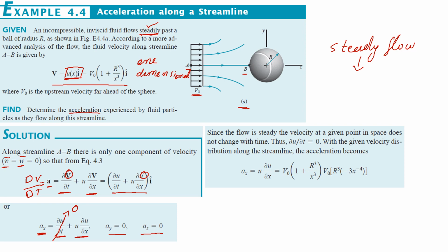And in this case, this was in material derivative. You know that our change with respect to time is our local change, and that local change is this one in this case, and that will be equated to 0 because here we are looking at the partial change in velocity with respect to a partial change in time. So that is why this component of this equation will be equated to 0. This is how our final equation will look like, in which we are going to put our values. So our acceleration in the x direction will be equal to this particular term only, that is u times partial u over partial x. So this is only our convective term.